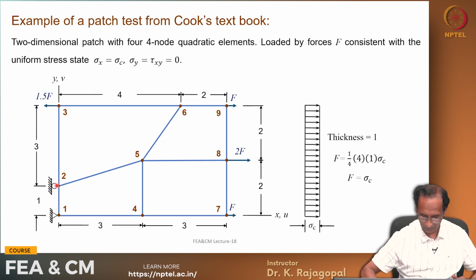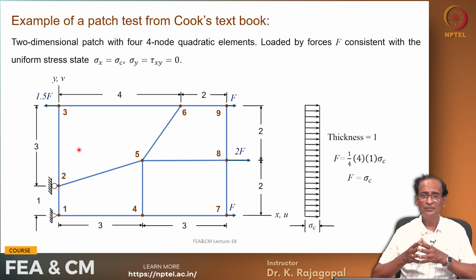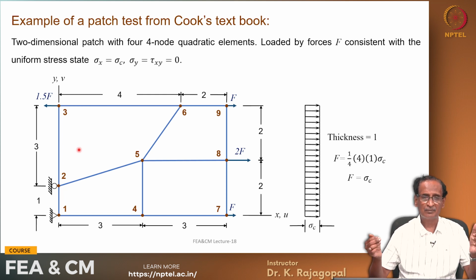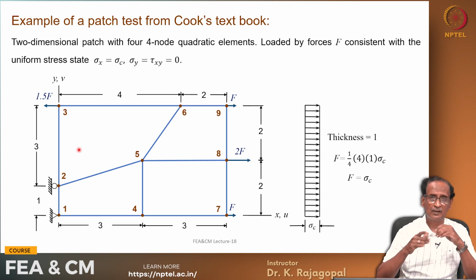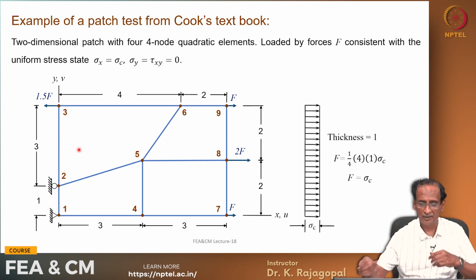and here this is put on a roller, and then there is some Poisson's ratio and some Young's modulus given. Then we do this analysis, and if we calculate the same constant stress all through the mesh, that means that the elements are passing the patch test.